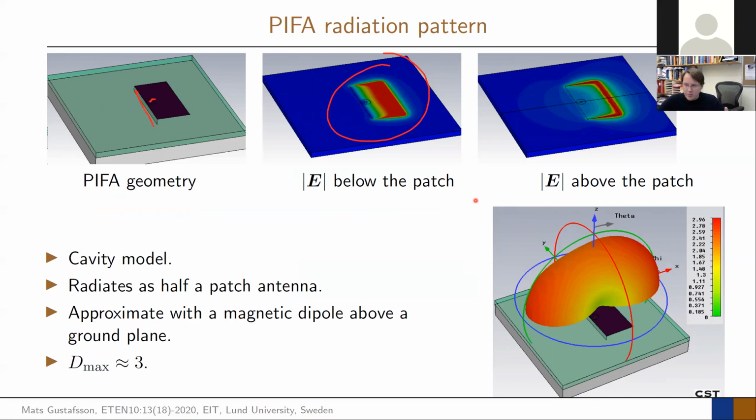If you now remember back to lecture 5, there we showed this pumping cavity field under your patch. So plus on one side, minus on the other side, pumping up and down. Now it's only one of them, pumping up and down. We took away half of it. If we look at the field above it, we can see very strong fields here on the edges. And really the strongest one is the one that sits here, and that is what dominates the radiation that comes out.